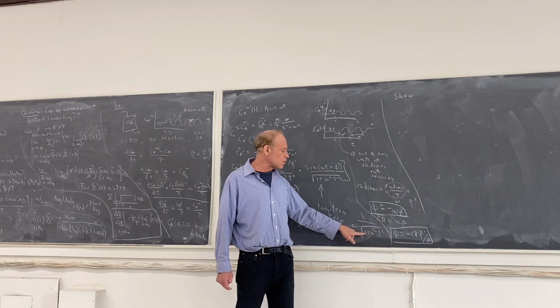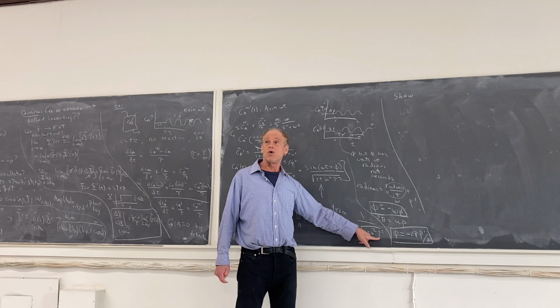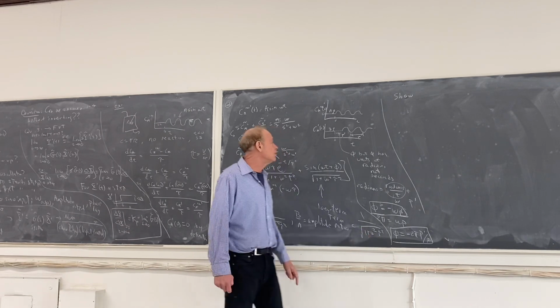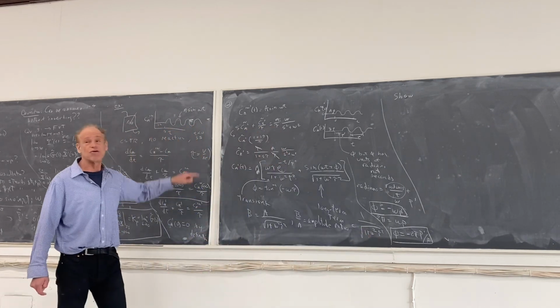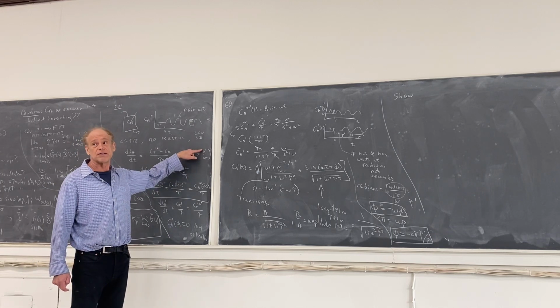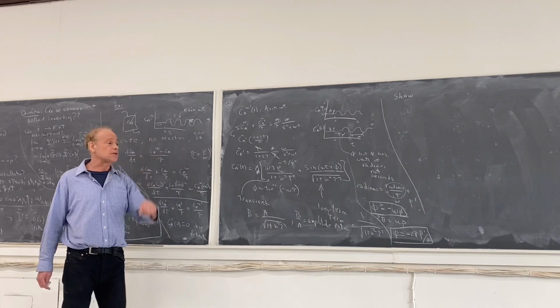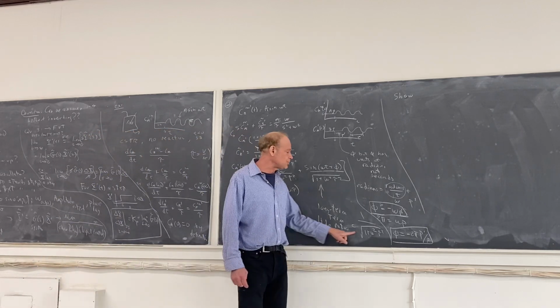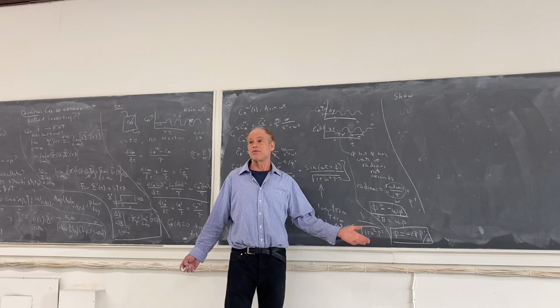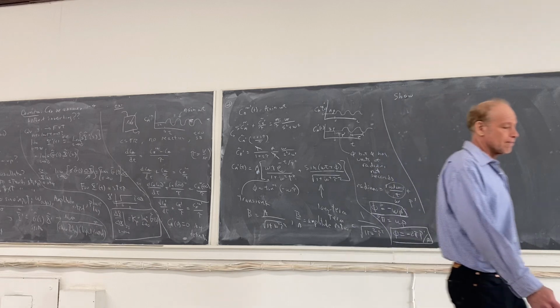If I set it equal to 1/10, omega is known, I just solve for tau. What tau will make it 1/10? And tau, remember, is big V over little v. So it tells me how to adjust the volumetric flow rate or how big to make the tank so that the output over the input magnitudes, the amplitude ratio, is less than 1/10. So hopefully I don't have to write that out, but that's sort of straightforward.